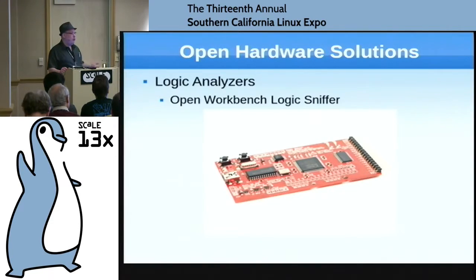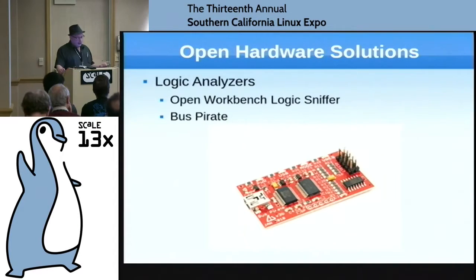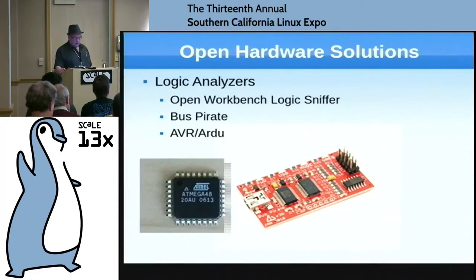This is a piece of open hardware that's been created to allow you to do logic analysis. It works for I2C, SPI, half a dozen other things, including CAN bus, and it's programmable and supported under Linux with open source packages such as SIGROK. Another one is the Bus Pirate, and it's a very simple board. There are some tight pitches on it, but in general, most people can solder this by hand, especially if they have a good scope or something that they can use. But it's completely open for anyone to use and manufacture themselves.